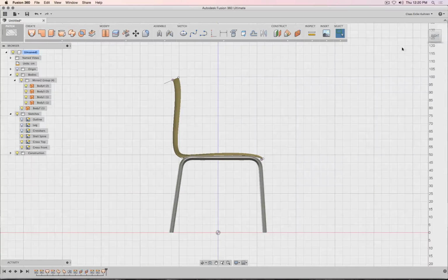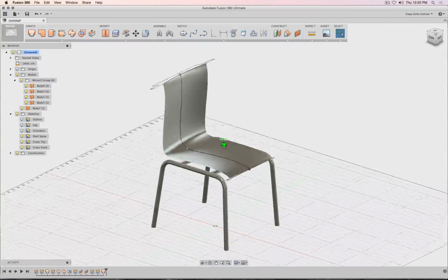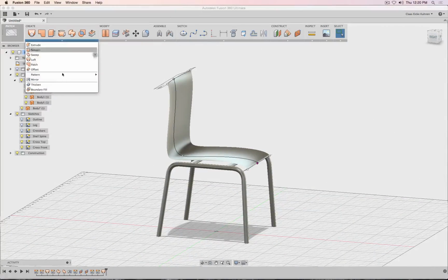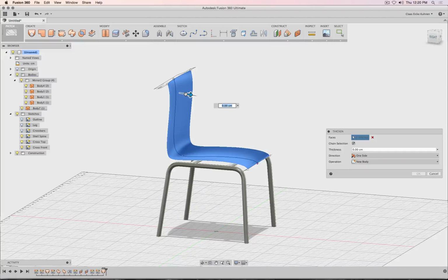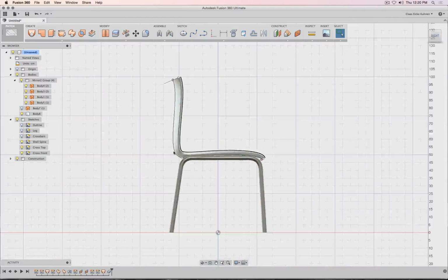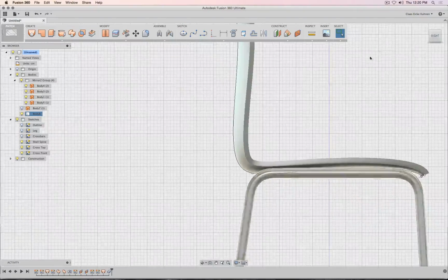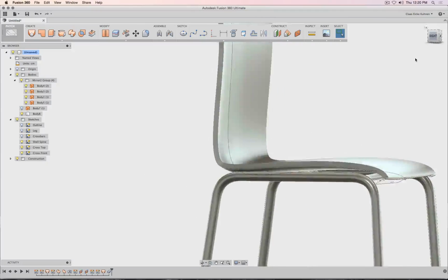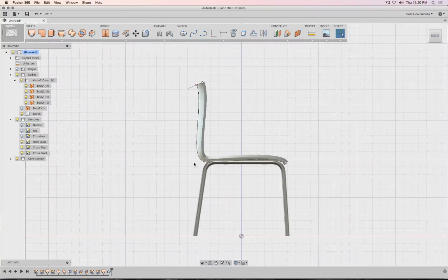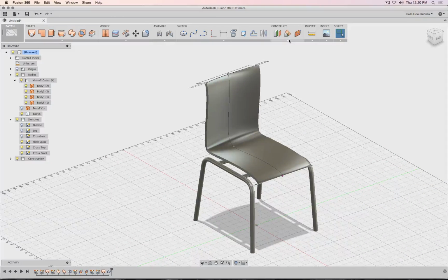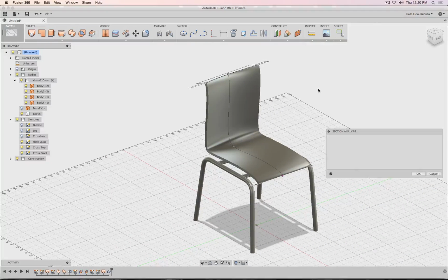Okay, so that doesn't look too bad. Let's add a thickness to it. Maybe, let's say 0.5 centimeters. So if I shrink the surface, keep in mind with a tight radius, it will get tighter. And now I really would like to see how everything looks at the midline. So I could, for example, use my section view. And show me the origin there, this one.